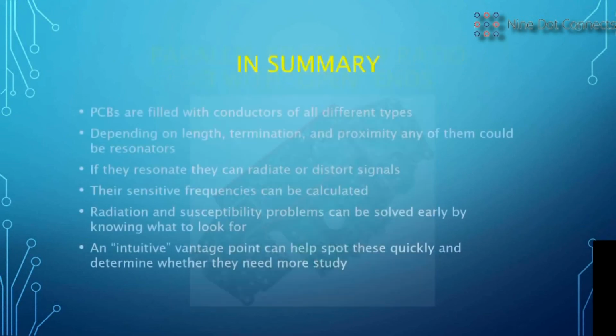In summary, PCBs are filled with conductors of all different types. Depending on the length, termination, and proximity, any one of them could become resonators. There are a whole lot of them. They all have to be checked. So how are you going to do it? You need to do it quickly. If they resonate, what can they do? They can radiate energy, such that you don't pass your emissions or you become susceptible to other EMI, or it can distort the signals. Their sensitive frequencies can be calculated.